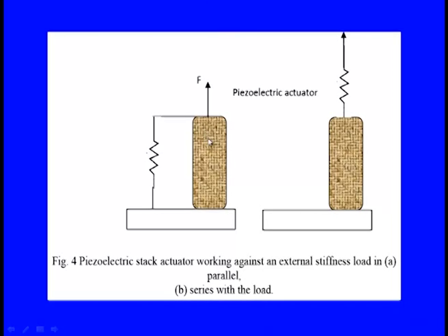So you see here, the forces are there, and in parallel, when we apply the external stiffness, the actuating force simply works against the restoring forces coming from it, and they can balance the entire feature shown on the below side. And you see here, this piezoelectric stack actuator can work against the external stiffnesses in the series formation, and can bring the entire structure to 0 amplitude by applying force against this part.